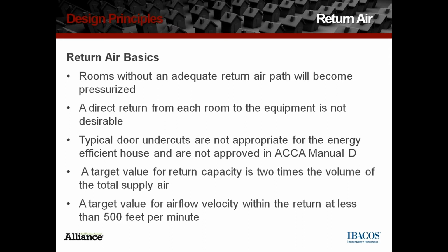The reason that return air is so important, and that a clear path from every room with a supply is needed, is that rooms without adequate return air will become pressurized. As the supply air enters the room, if it doesn't have a clear route out for the mixed room air, you will pressurize the room like a balloon, and you can slow down or impede that supply air's path into the room.